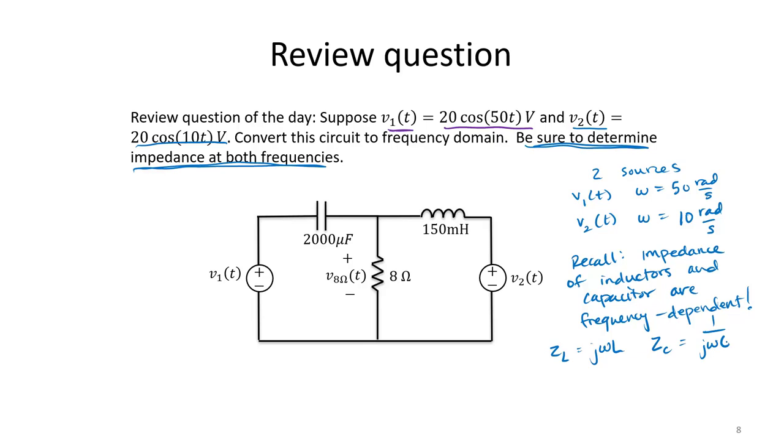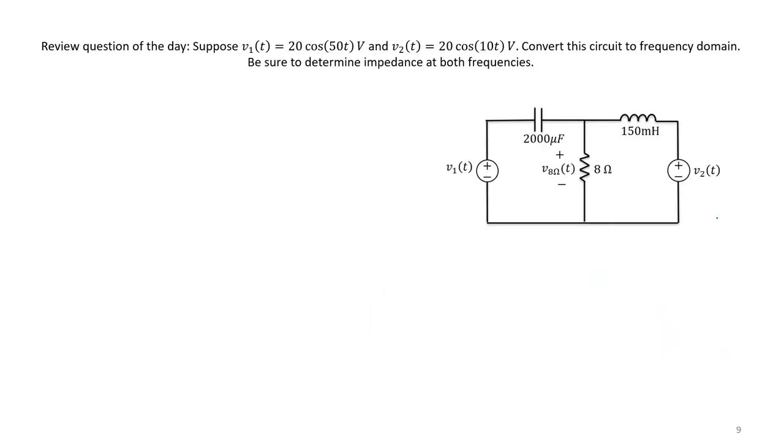So you'll notice in this case that depending on which frequency we are operating in, the impedance of the inductor and the capacitor will be different. For now, let's focus on just determining what these impedances are, and a little bit later in the video, we'll return to this question and apply superposition. So let's go ahead and convert everybody to frequency domain.